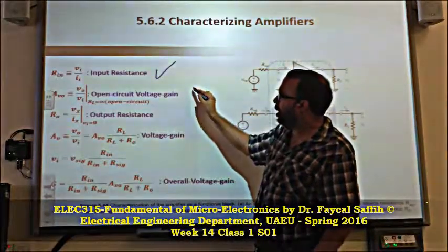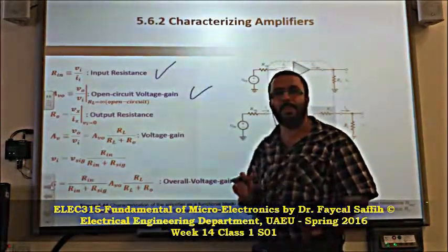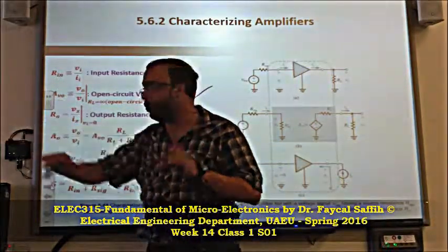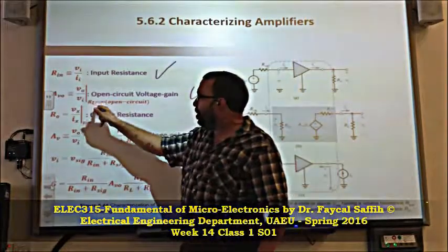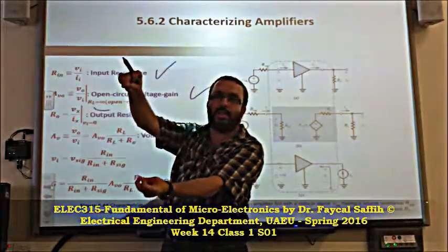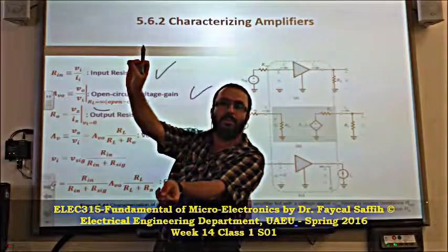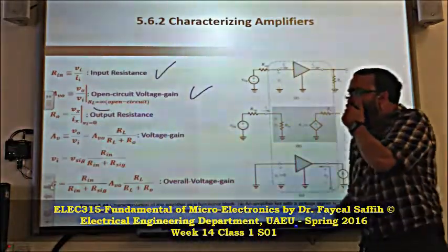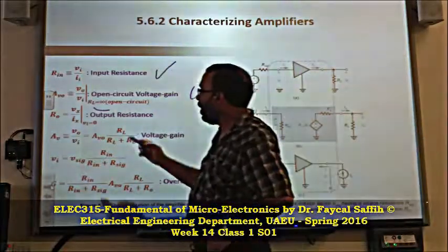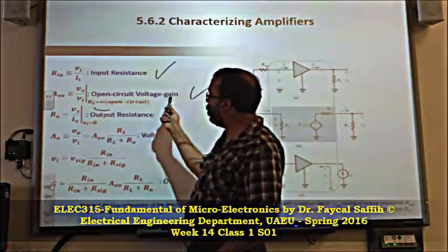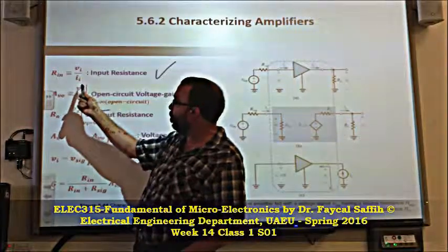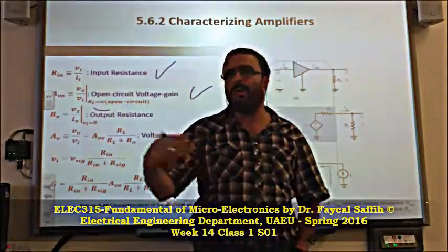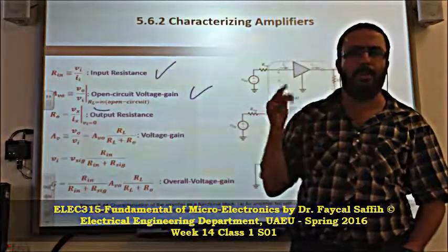The second characteristic is the open circuit voltage gain. It means I have the amplifier but no load at the output. No load means a big resistance at the output, or it's open, same thing. Here we are talking about the open circuit voltage gain, that means output voltage divided by the input voltage, without any load, or with a load that has an unbelievably big resistance.